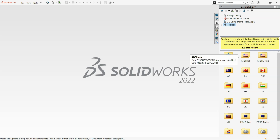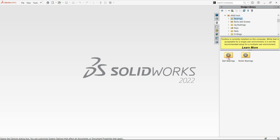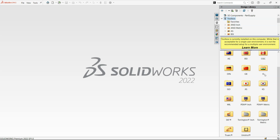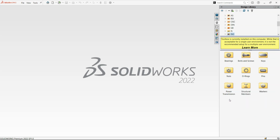For example, let me open the ANSI inch. By opening the ANSI inch we get bearings, bolts, screws, jigs, bushings, etc. So let's say I need a ball bearing. I will go in here, and there are multiple types of ball bearing, and in every bearing we have multiple configurations, like the sizes and diameters we want, which all depend on our requirement. There are multiple standards given here in the toolbox: GB, KS, ISO, JIS, ANSI, metric. So it is a very handy tool and very useful in the assembly environment.